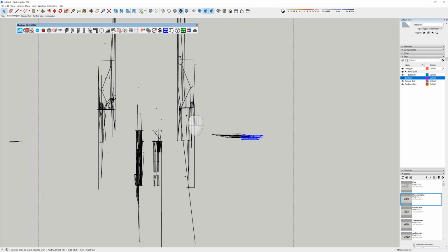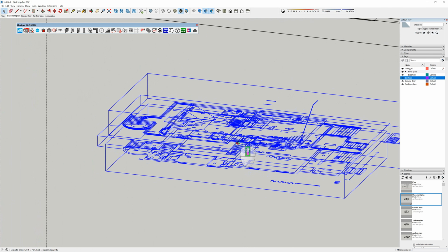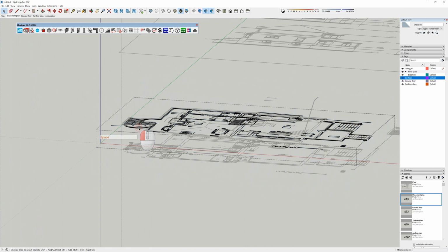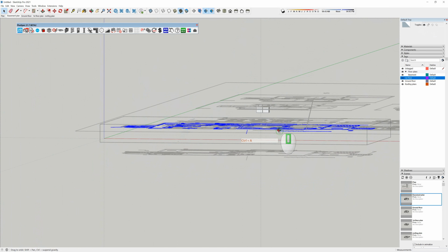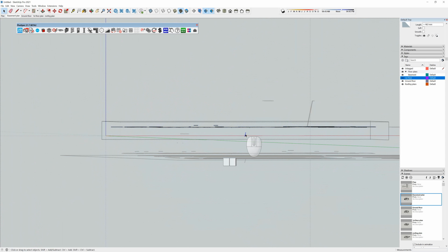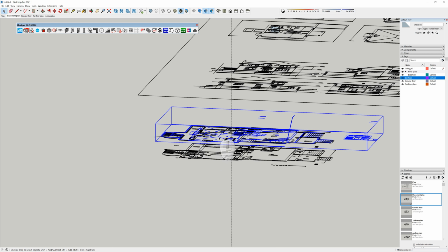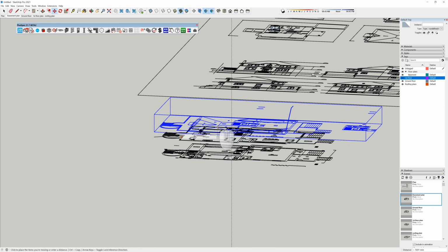before, you'll notice that the things weren't all drawn on 0, 0 axes, and that can be a little bit difficult. What to look for is to triple click on the plan, or Control A, and see which items are actually connected to the ground floor plane. You can see there's one there. I can delete that. I can then move that plan individually up to the distance that it shows on my elevations.